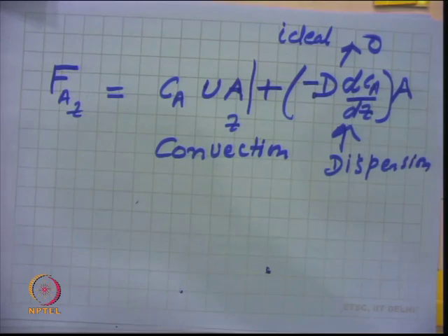So, this is very important to study, because this will affect the performance in terms of conversion and selectivity. When you take a commercial reactor from a small scale reactor and scale up, the properties may not remain the same, so we try to look at dimensionless numbers, as I said Peclet number yesterday, the dispersion number D upon UL, a kind of non-ideal parameter.